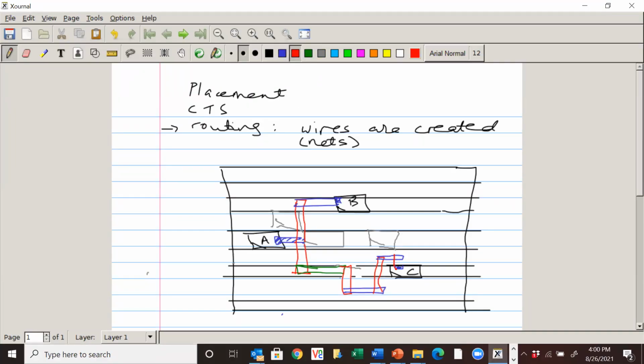It has to get to the pin, so it goes back in metal 3, and goes to metal 2 here to make the connection. Between all these different metal layers, there will be vias. There will be a via there, a via here, and a different via out there. So all this, what I'm doing manually, will be done automatically.